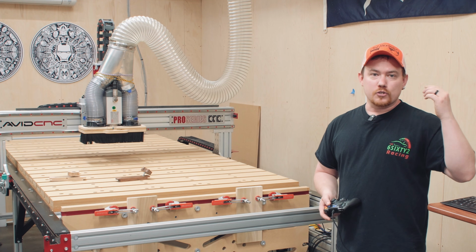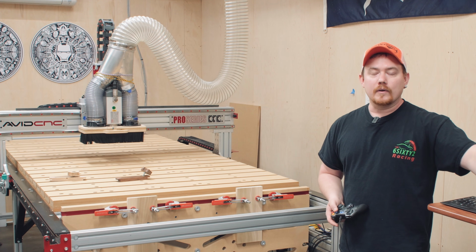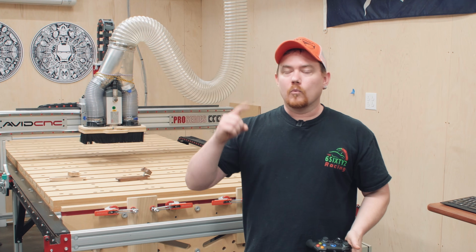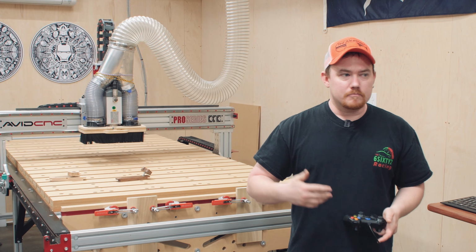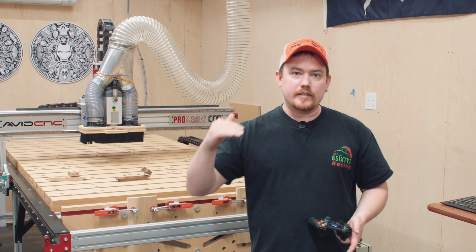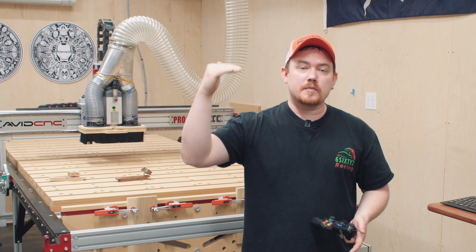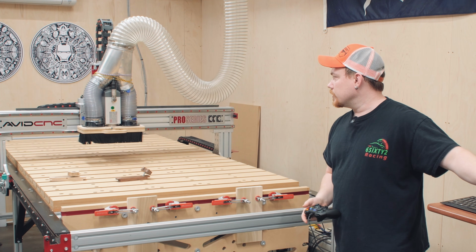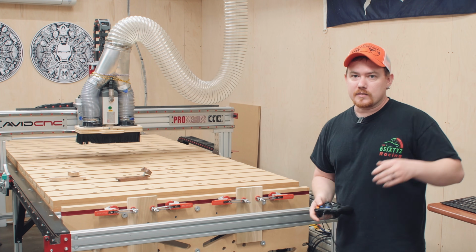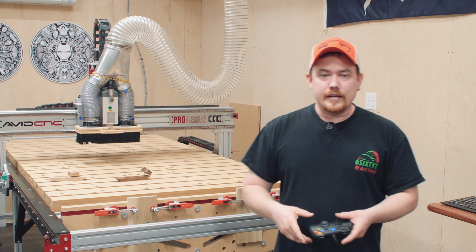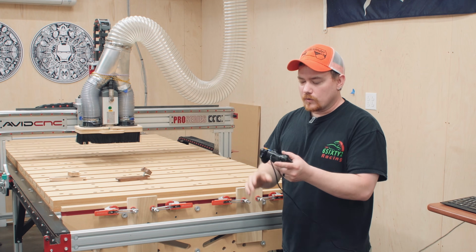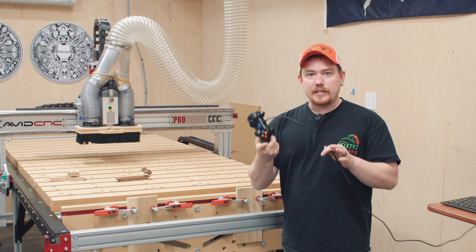And then if you press control and then a directional arrow, it'll incrementally move a specified distance. So 1 inch, 0.1 inch, 0.01 inch, you can specify the increment in which you want it to move a specific value. So control, and you're probably not going to see much movement there, just wiggling basically. That's very, very handy for your Z-axis height for the vertical table. So how does all of that translate to the video game controller?